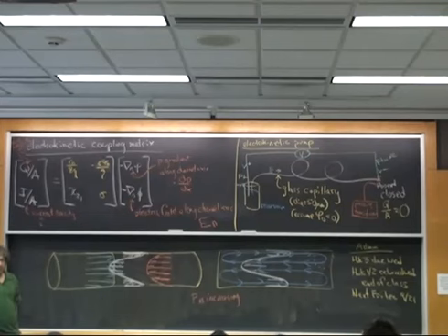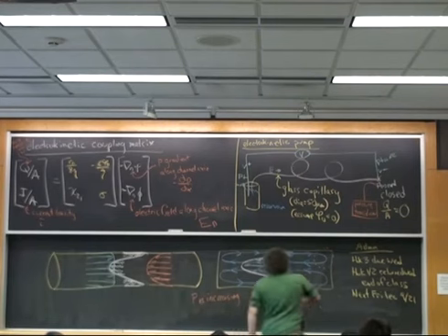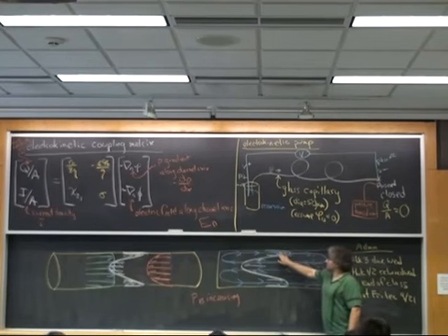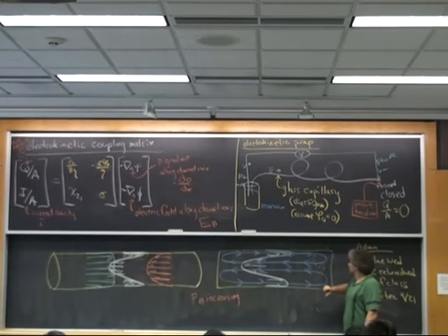There is an adverse pressure gradient, and in fact there is an adverse pressure gradient everywhere. And that adverse pressure gradient in its own way affects the velocity here and here and here and here. In fact, everywhere across this channel, the adverse pressure gradient affects it. In the center, the adverse pressure gradient is dominant. At the edges, it's not.